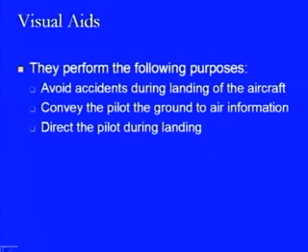They direct the pilot during landing. This is another important aspect, because as we have seen there are certain distances and certain points, like there is a touchdown point on the runway strip. Similarly, there is a lift off point on the runway strip. These points are all located on the strips in certain form, and the pilot understands that, and accordingly orients themselves so that they can use that particular area which is being specified for that type of operation.